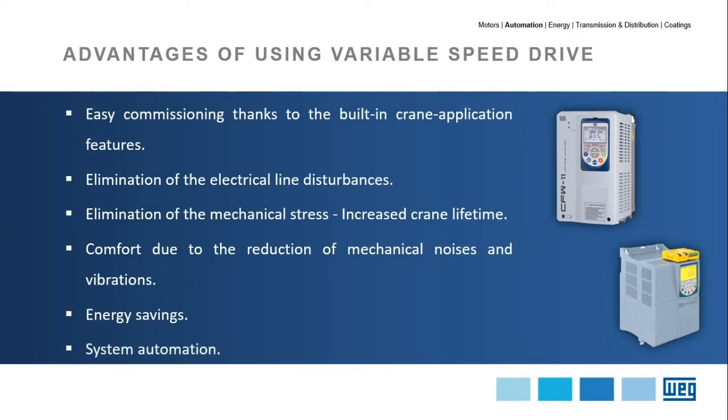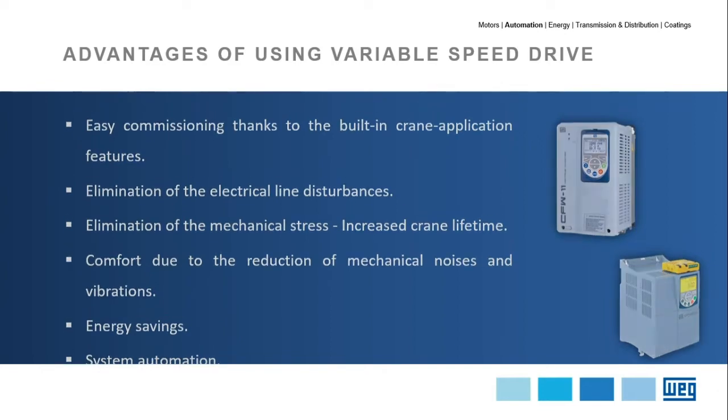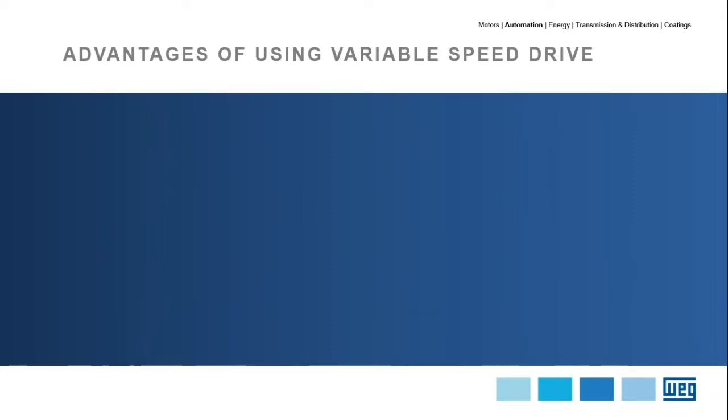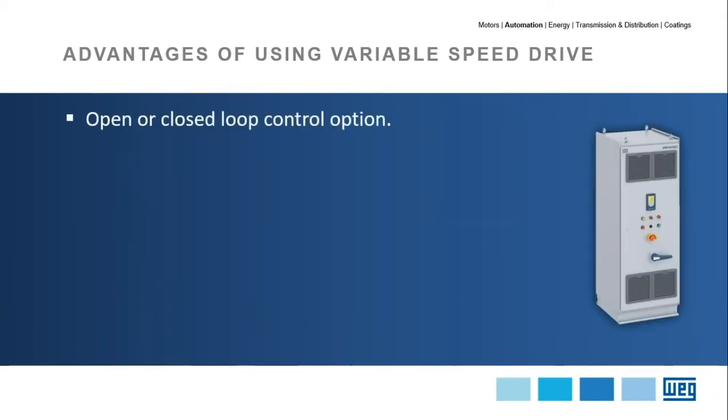System automation, so we have the possibility to integrate the VSD into a communication network, and from there you can have access to status, to control the drive, and so on. Open or closed loop control option is possible from the VSD.